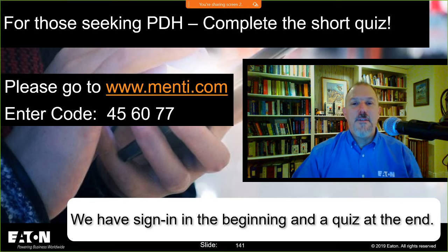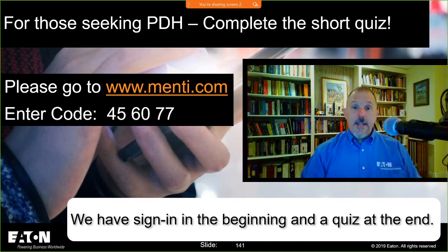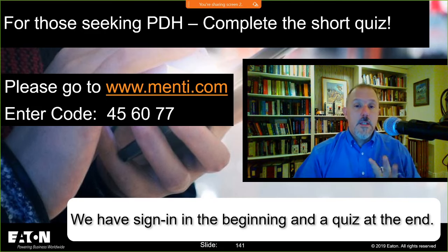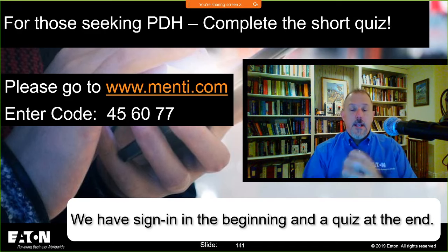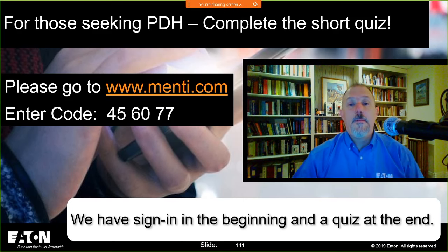Trip free means that the breaker will trip even if the switch is held in the on position. Yes, James, that is true. If you hold that breaker in the on position, it's still going to open when it says trip free. That's exactly right. Handle locks will not interfere. So if you put a handle lock on it and you're locking it, it's still going to trip.